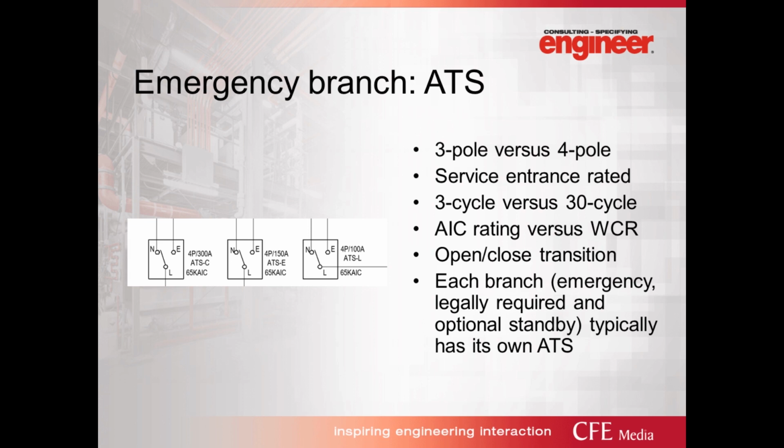The transfer switches are not rated to clear faults. Therefore, they do not have an AC rating. Per UL 1008, the transfer switches must withstand the fault current and also close on the fault current. The transfer switches will have withstand and closing rating. Each branch typically has its own ATS, referred to Article 700 through 702 in NFPA 70.